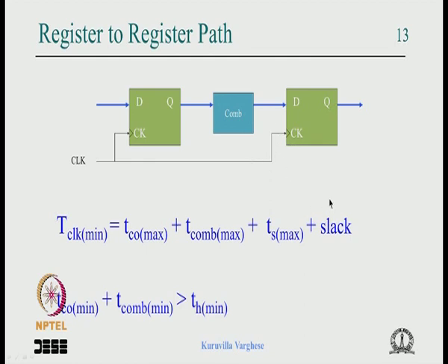And very many times people ask a naive question, why this cannot be the clock bar. As I said, there is no great issue with that. The trouble is that you are looking at a part of the whole, and if you keep the whole picture in mind, then you will soon realize that this is not possible, because this is clock bar, and again next is clock, that is fine, but then there is a feedback from back here, then you find the last one was clock and the feedback is also back to the clock, not to the clock bar.